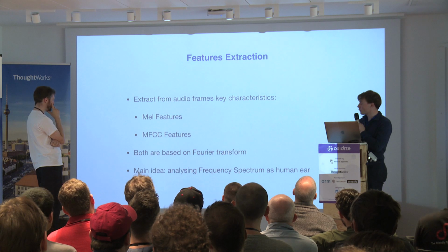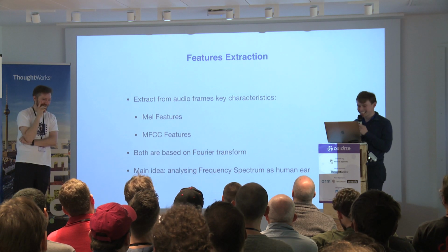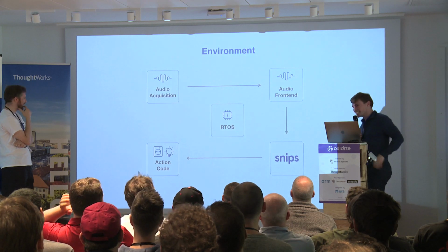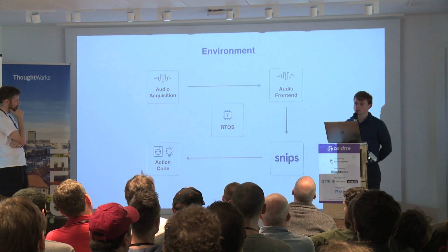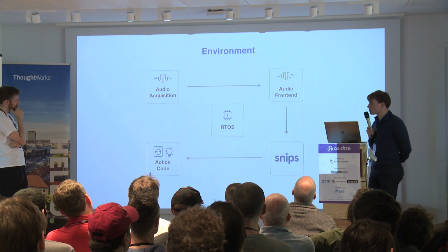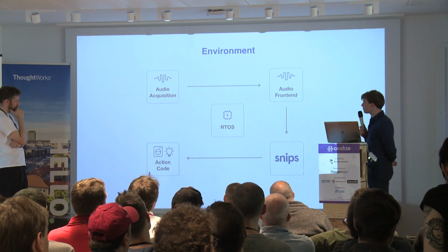So which RTOS are we using? It's FreeRTOS. But we are not dependent on any real-time operating system, because we act as pure functions to be sure that we can be integrated in a bare metal environment as well as with an RTOS.